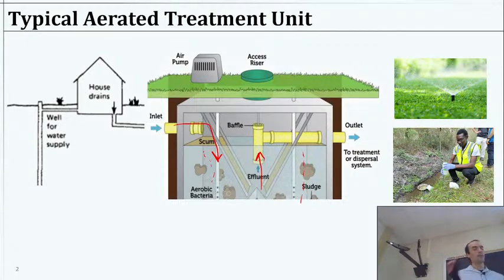So there's a lot of things that could block the air pump. These pumps sometimes will also fail. The way the pumps work, they can still be pumping, but the diaphragm breaks or degrades or something, and so it's moving, but it's not moving any air. That could happen too. So you're not actually pumping your air in. So there's several issues with this.